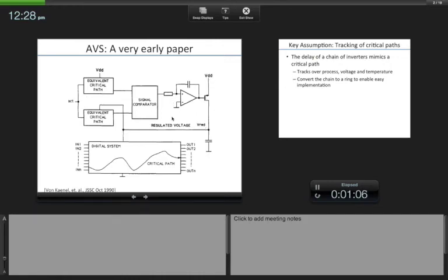Typically in a voltage regulator, there is a specific target voltage which is given as a reference of some kind to this op amp, and the op amp tries to generate an output voltage such that the generated voltage matches the target voltage. Here the target voltage is not a voltage, there's no specification as to what the voltage is. It's coming from the time domain.